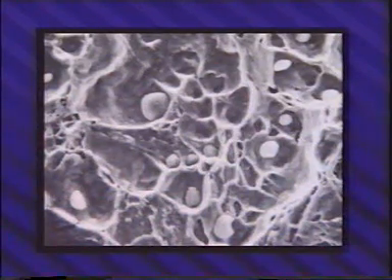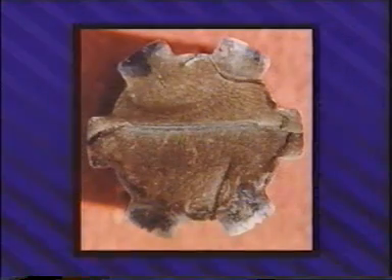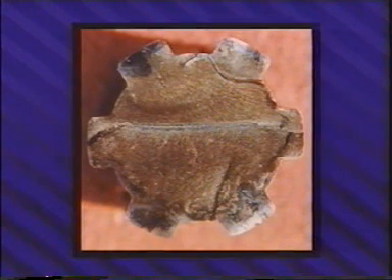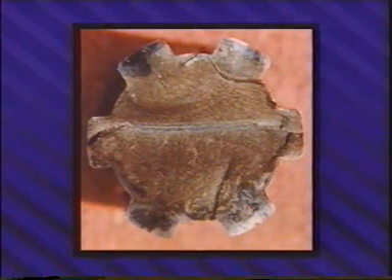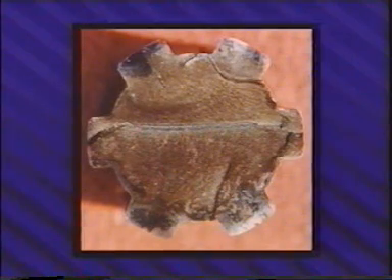The cracks initiate at points of maximum local stress. These points are determined by the shape of the part or by surface and metallurgical imperfections, such as scratches, burrs, or other fabrication flaws. Foreign materials and hard particles in the metal can also determine the site of crack initiation. A great number of fatigue failures in otherwise lightly loaded structures originate in fretted or rubbed areas. In any jointed structure with some relative motion at an interface, fretting provides a possible location point for the initiation of failure.